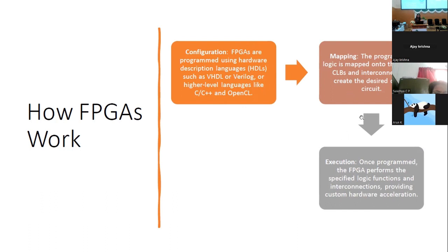Then after that, what we will do is execution. The software will give a binary output. It is called a bit stream. This binary output that we get from the software, we can execute inside the FPGA. This is how to create hardware inside an FPGA.